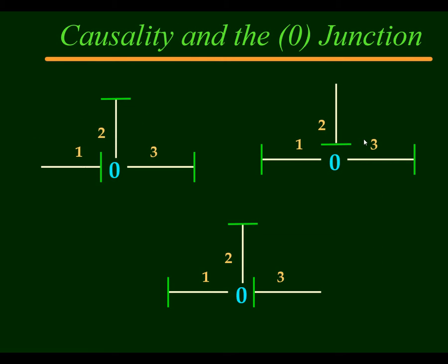But if we put the causal marks, one of the things that we really need to emphasize is that only one of the bonds would set the effort to all the others, or set the flow for all the others, but in this case, the effort. So you say this is the effort here. So it comes from some place in the system over here, this way.